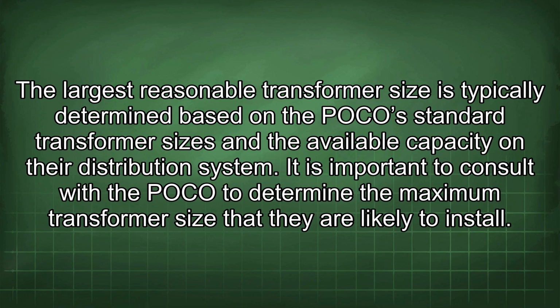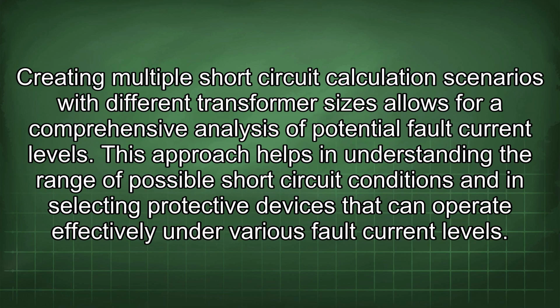The largest reasonable transformer size is typically determined based on the POCO's standard transformer sizes and the available capacity on their distribution system. It is important to consult with the POCO to determine the maximum transformer size that they are likely to install. Creating multiple short-circuit calculation scenarios with different transformer sizes allows for a comprehensive analysis of potential fault current levels. This approach helps in understanding the range of possible short-circuit conditions and in selecting protective devices that can operate effectively under various fault current levels.